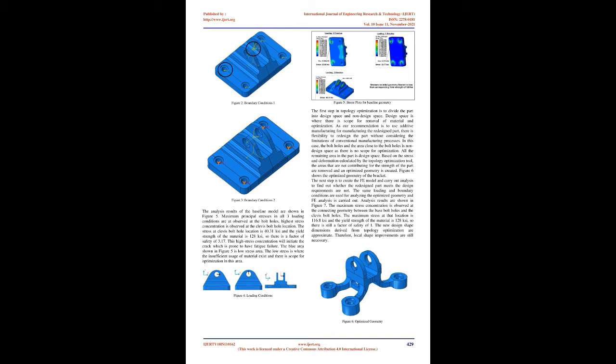Kinematic couplings are used between bolt holes with a reference point in order to simulate bolts, and at the clevis location in order to apply the load, refer to Figure 2. Bolt holes are constrained in all DOF as shown in Figure 3. Equal loading of 8000 lbf is applied in all three directions, global X, global Y, and global Z, as shown in Figure 4. Table 1, Material Properties of Titanium. Property. Value. The analysis results of the baseline model are shown in Figure 5.